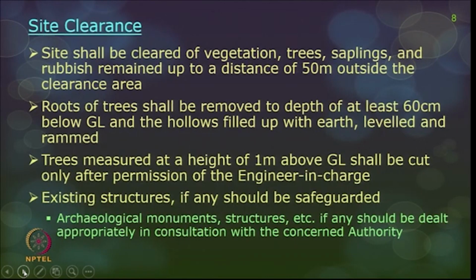Then the next step is site clearance. As I told you, you may have to first clear and level the ground before you start with your excavation. So, what should you think of for site clearance? Before site clearance itself, if there are usable structures, existing structures, trees which you want to safeguard, or archaeological monuments and structures, then you should get proper permission for safeguarding them, so that your excavation work does not interfere with them.